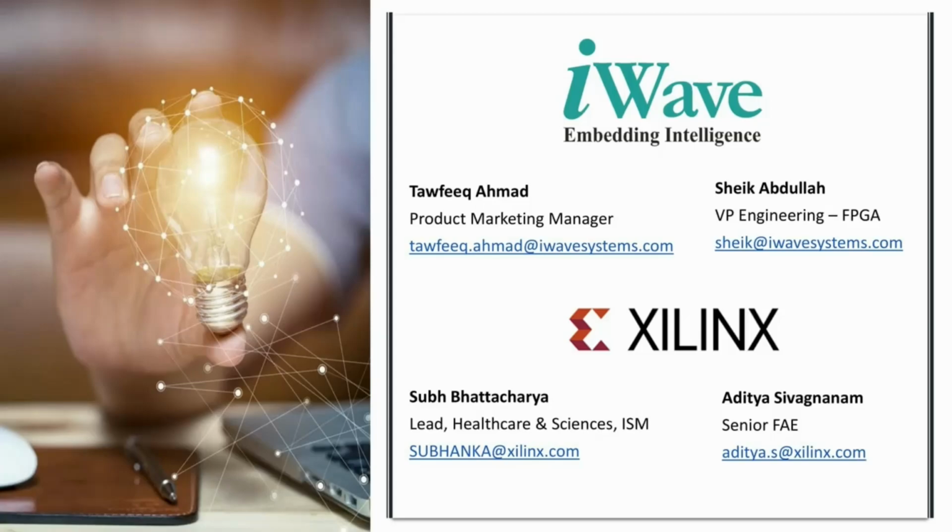I can add to that. Sheikh, are you able to hear me? Yes, Adi, please. It depends on what you mean by high speed. If you want to do more than 1G, we can use the transceivers. The transceivers are also brought out to the SOM connectors, and you can use that on the carrier card. But if it's less than 1G and you're using just the standard IOs, LVDS, you should still be able to achieve Ethernet connectivity. Many of our SOMs today already have that, right, Sheikh? Yes, you can confirm. Adi, thank you for your validation.